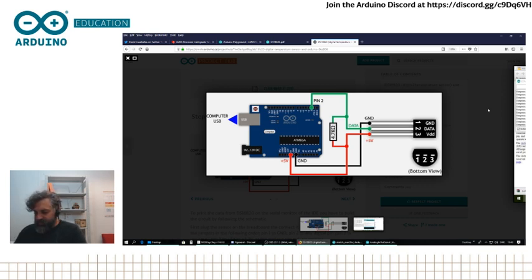And the power cable is at the other end. And the important thing here, remember, is that we need a pull-up resistor according to the circuit. And I'm going to take a 10 kilo ohms resistor. Even though here he's using a 4.7K, I'm hoping that it will work fine with this one that I'm going to put. If it fails, I will probably have to change it. So I'm going to be very creative with the circuit. I don't like to make it this crowded, but I'm just trying to make it very quickly for the show.